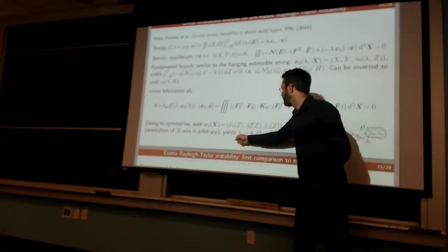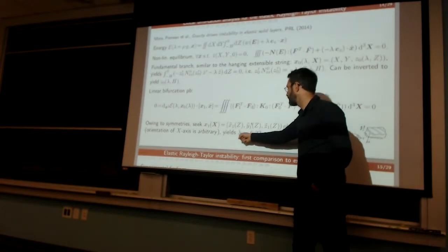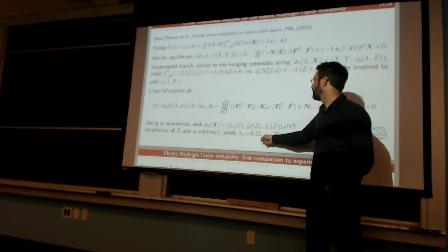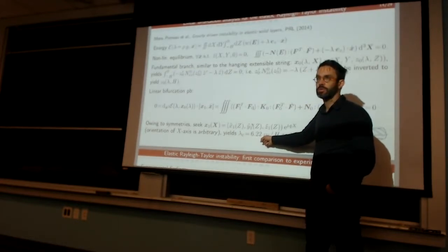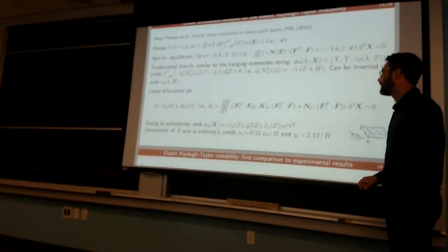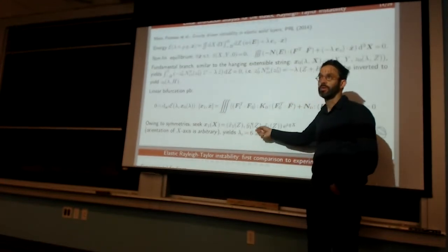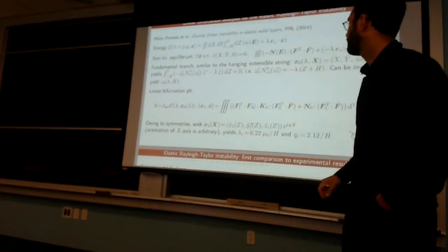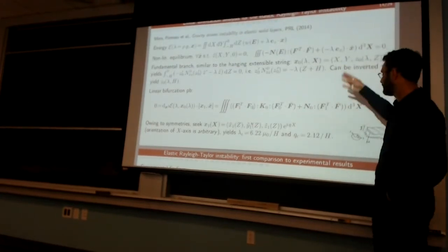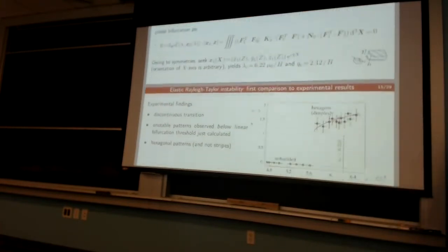The critical value of the load, and you find a universal value. So the real bifurcation parameter would be the ratio of rho g to the shear modulus times the thickness. That's just by basic scaling analysis. And you find that this parameter has to have some magical value for the first bifurcation to take place. And you can also, like in the problem I was showing before with the sphere and the film, select the wavelength. So let's see what that gives.